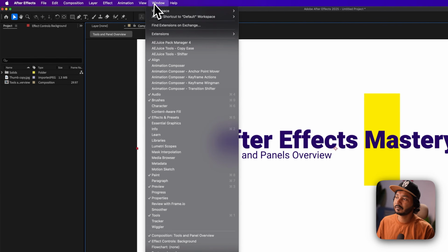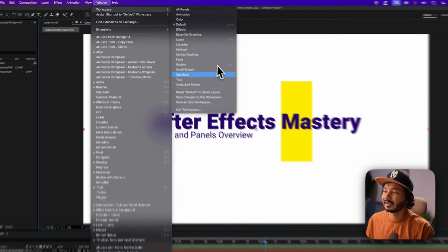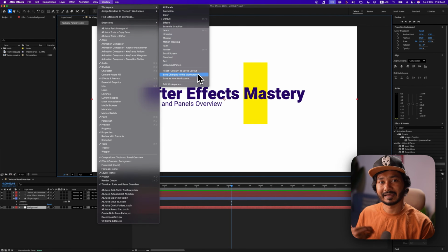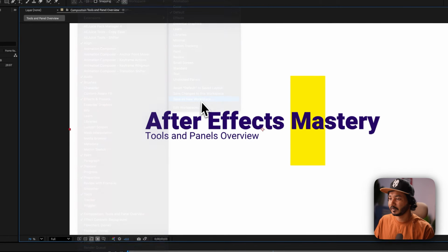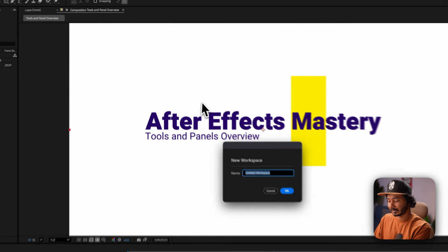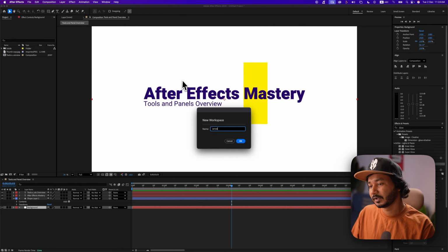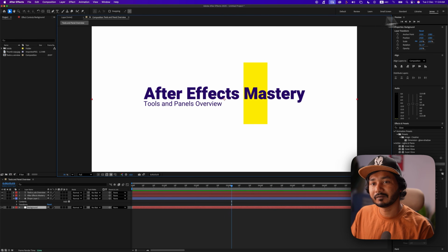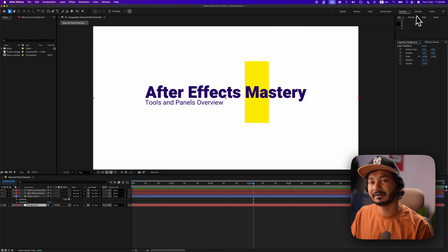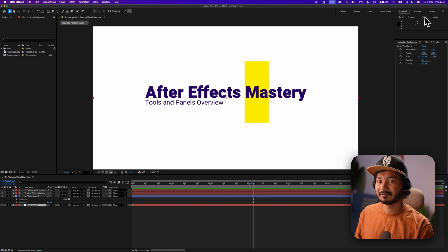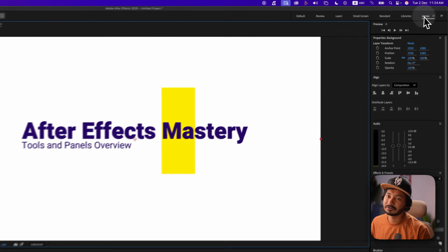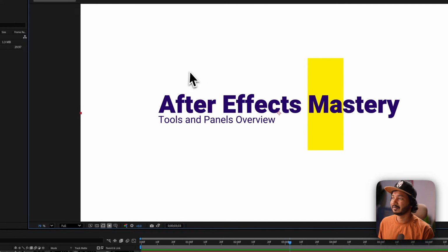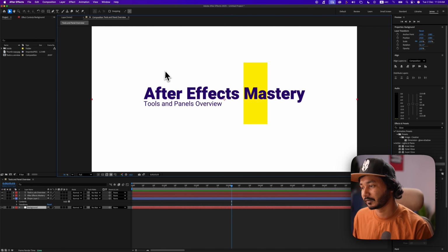And if you go to Window and then Workspace, you can save that. Suppose I want to save it with my name, James, right? I can go to save as a new workspace, and then I can write James, and if I click OK, it will make a new workspace. Now if I want to activate James, I can just go there. Suppose I am here on standard. Now I want to go to my saved workspace. I can just click on James. It will show me the panels that I need for my purpose or for my needs.